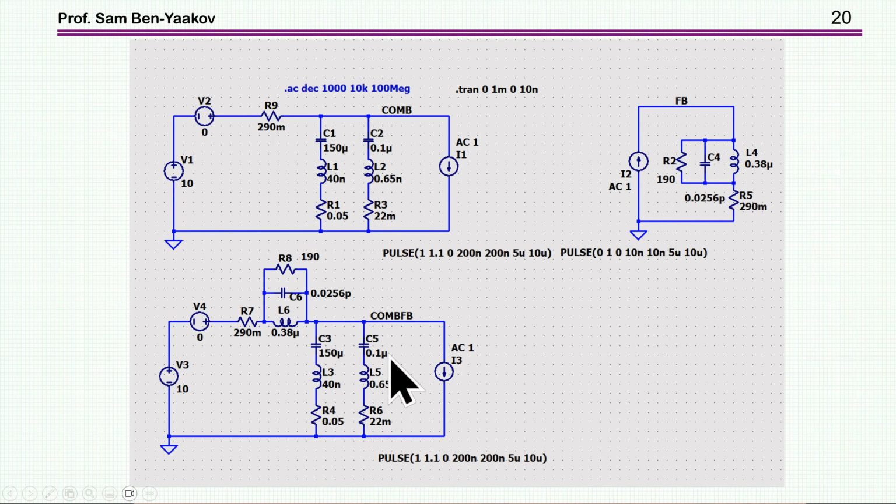So I'm now showing the effect of this ferrite on the decoupling circuit. I have now a source, a switcher. It's 1 amp with a 100 milliamp pulse riding on it. I have here an electrolytic capacitor. I have here a ceramic capacitor, 0.1, according to, well, let's call it the book. Everybody knows, well, you have to put a 0.1 microfarad.